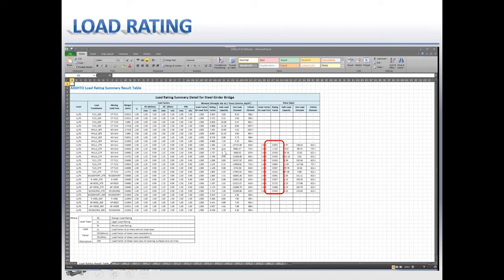Alright, so I want to point out here that my shear is basically pretty much failing for all of the cases. And here's where we're going to get into the troubleshooting part of it. The reason why all of my elements are failing for shear is because MIDAS in the load rating section, when it's calculating the shear, is not technically accounting for both of the webs in the tub girder. It's only accounting for one of the webs.